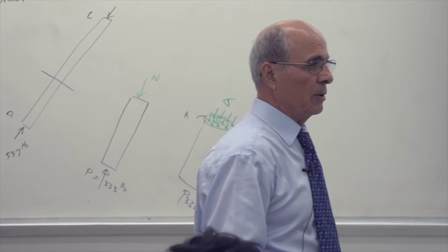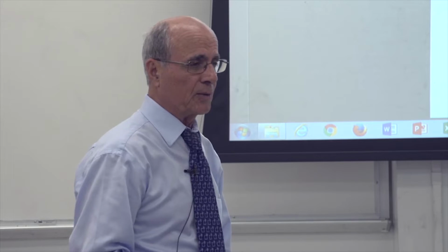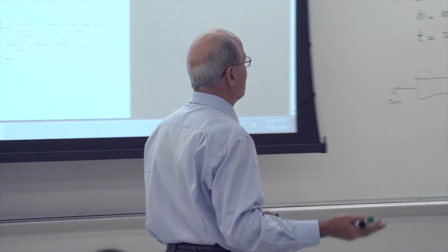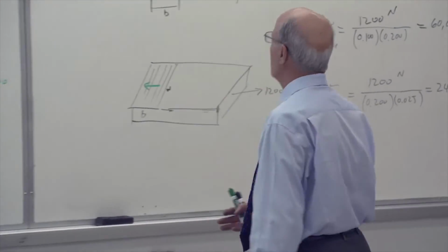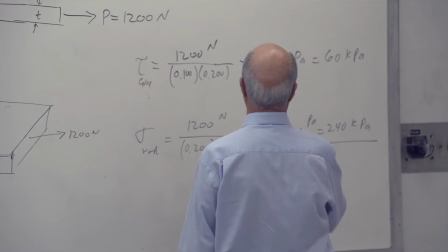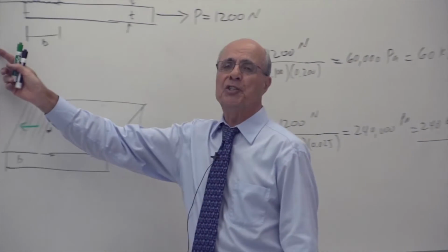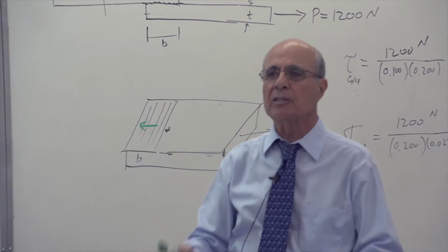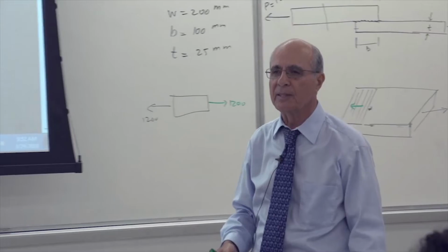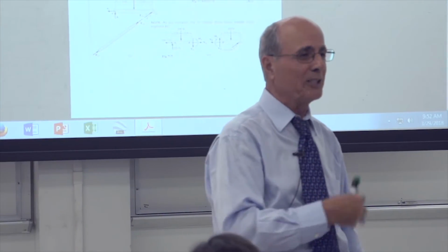Yes? Couldn't you just increase the area? Oh, of course, yes. Good question. Again, good answer. But I'm just trying to show you another part of a structure. Yes, she said quite correctly that if this is too much for my glue, I can increase this B. Everybody understand that. So I have more glue area, so stress becomes less, obviously. But I'm trying to teach you another alternative of the system to find out what's going on.